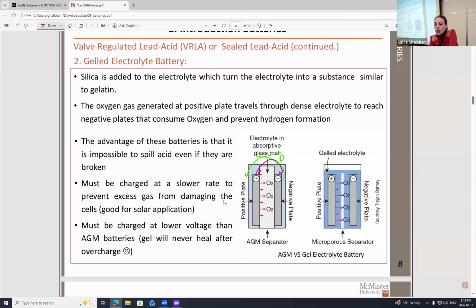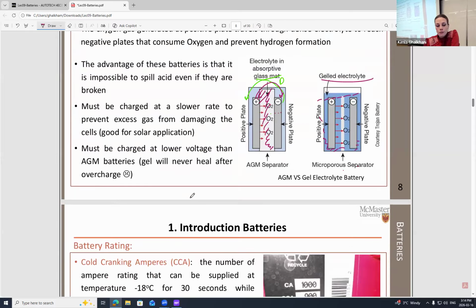And always, whatever we have in the electrolyte is going to make the process easier. So if we have the porous electrode, everything is around the two electrodes. For the fiberglass, it is in between them. The entire layers here and here are not covered, only here is the fiberglass. But with those porous electrodes, this whole blue part means the liquid covers the entire electrodes all around them, regardless of how many layers of electrode we have.